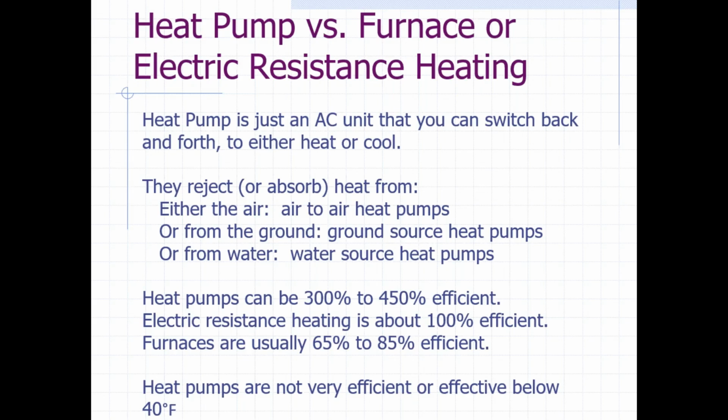Now furnaces take gas, often natural gas, or maybe something else, but usually natural gas, and they burn it. And that efficiency is maybe 65 to 85%. But heat pumps are different. Heat pumps are using that refrigeration cycle I just talked about.